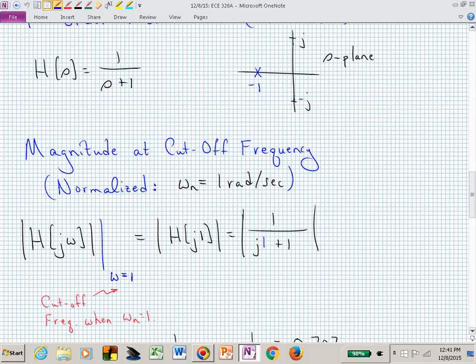Yes? Is the gain the numerator? Is that like the coefficient? So the question is, where's the gain, or what is the gain? And you have a gain at all frequencies, don't you? But people use that term maybe inconsistently, but ideally if you said, what's the gain, you would say, okay, let me put this transfer function in time constant form, and what's the coefficient or the constant that comes out independent of all of those other factors? And that would sort of be your gain.